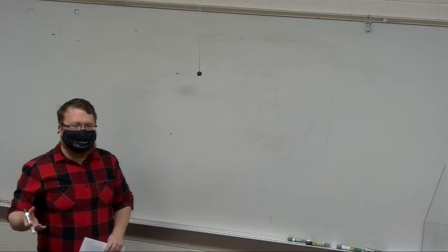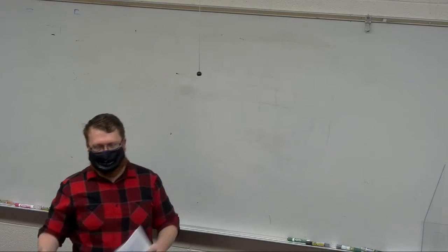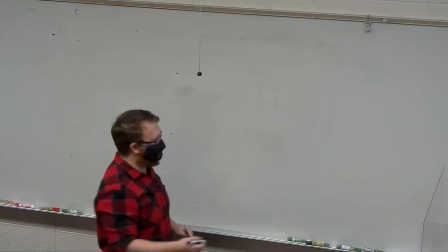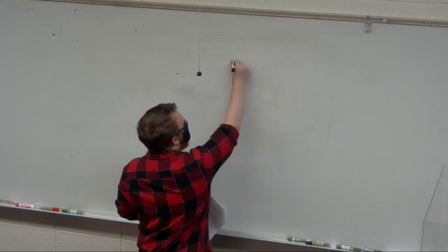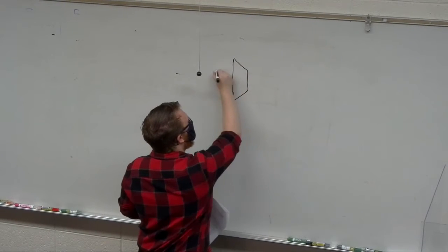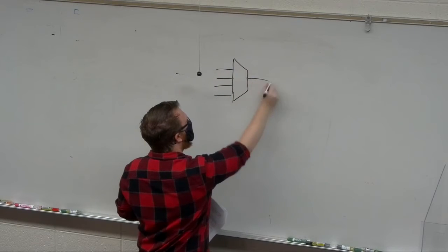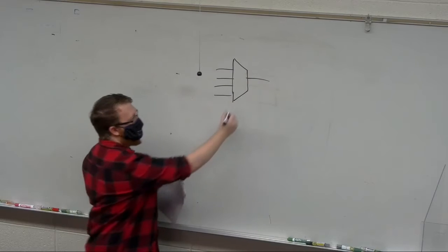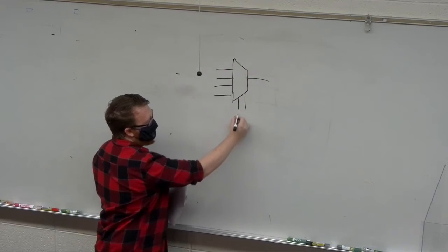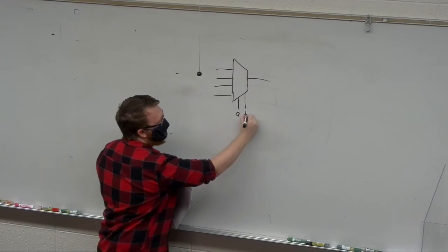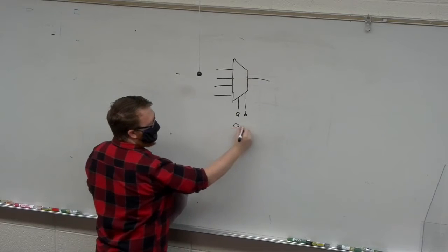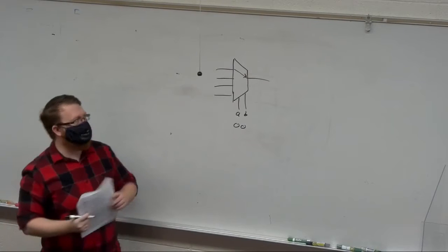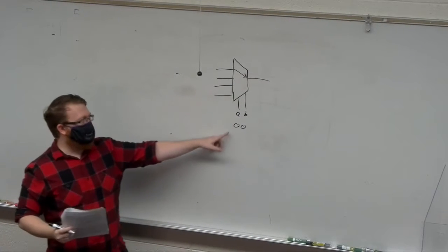So like if you went out and bought an Analog Devices 4-input mux, right? A mux is just a switching device, has 4 inputs, and it just chooses one. So it would have selection bits, A and B. If I selected 0, 0, it would connect this input to the output. And that's how you control it.